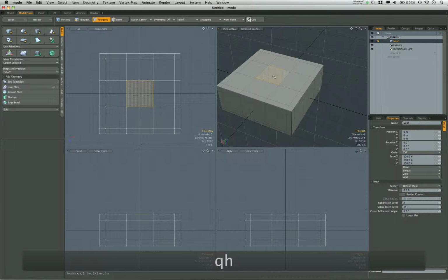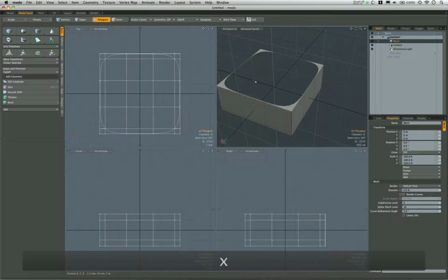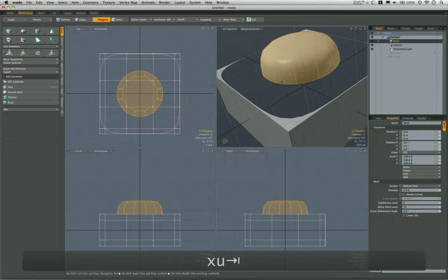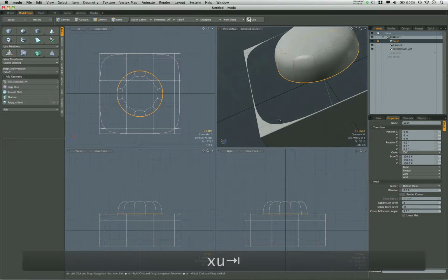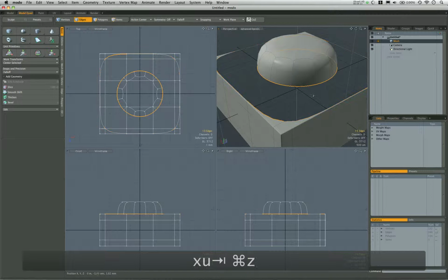I'm going to hide this piece, and then I'm going to select and then shift up arrow to select the outer edge of poly, so I get all 9 polygons in the middle here. And we'll cut those out, and then we'll unhide our middle. We're also going to need to subdivide that since it's going to be connected to a subdivision piece. And then I can select the boundary there just by holding down Control and clicking on Edges. Again, I'm going to select this outside edge. So if we go over to Lists, we should see how many sides we have selected, and it should be 12. We can see down here we have 12 edges selected, and then when we select all of this, it should double to 24.